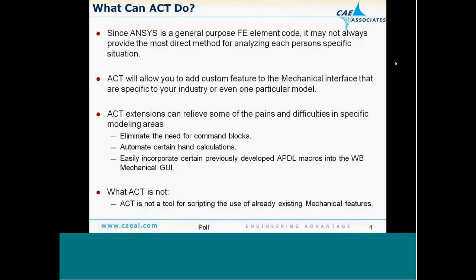And it looks like mainly either reusing APDL macros or a new load or boundary condition. And I'll say the way that is set up with ACT, they're really sort of the same. You're essentially replacing either an APDL script, or your new load or boundary condition would be some type of APDL. So they're really kind of the same in terms of what would be required from you to do that, but again, different uses. So that's certainly a majority result quantity.